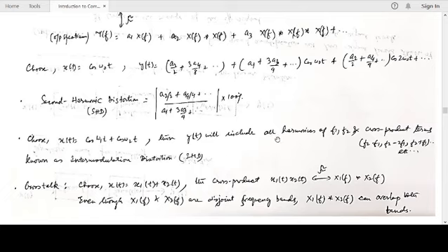So y(t) will include all the harmonics of f1, f2 and also the cross product terms between these two frequencies. Hence this is known as intermodulation distortion. These resulting signals are known as intermodulation products. We need to characterize how much intermodulation distortion is provided by the nonlinear system. That is also a figure of merit.